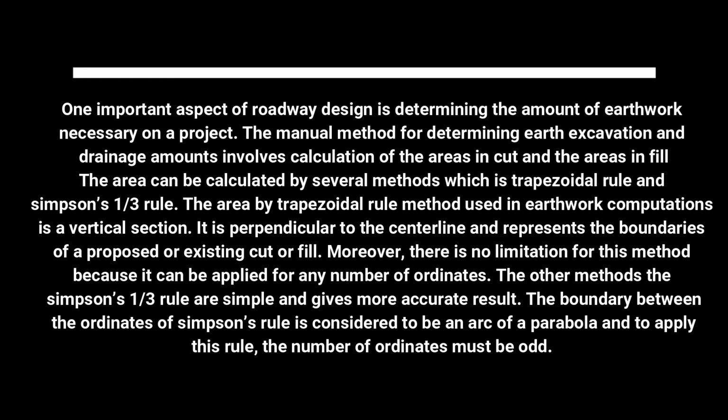Another method is Simpson's 1/3 rule, which is simpler and gives more accurate results. The boundary between the ordinates in Simpson's rule is considered to be an arc of a parabola, and to apply this rule, the number of ordinates must be odd.